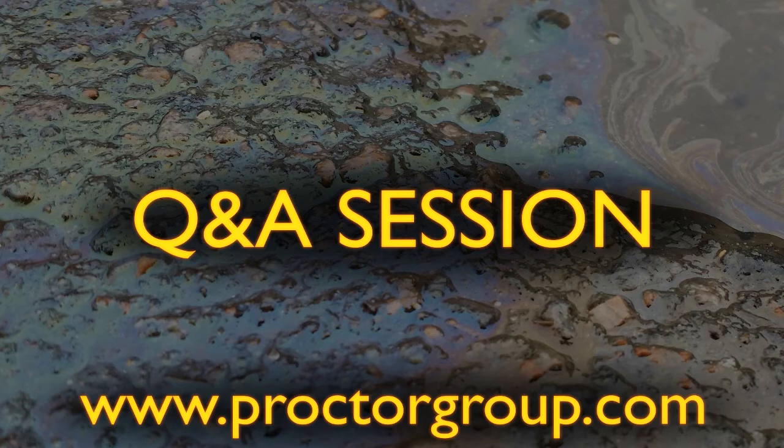Okay. Can liquid applied membranes be used in VOC contaminated sites? Again, there's a lot of liquid applied membranes that have a certain amount of hydrocarbon resistance, but they won't be tested to the same criteria and tests that are in 748. So again, it would be a case of having a look at the particular hydrocarbon and the concentrations of it, and depending on what sort of liquid applied membrane you're using, whether it's acceptable or not.